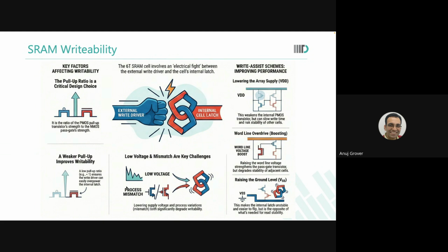You design a charge pump with 25% boost. But at 0.9, you said, now I don't want 25%, I want only 12%. At 1.0, I want 5% only. So your charge pump design is far more complex than what meets the eye.